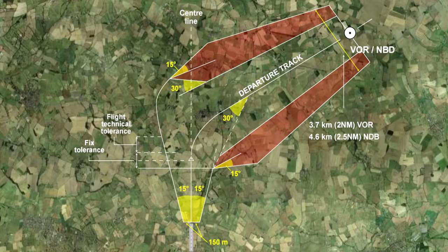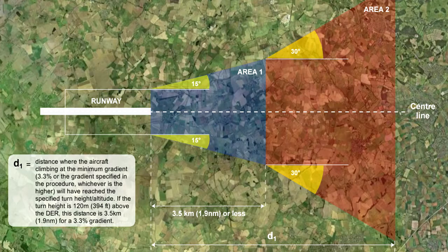In the event of in-flight emergencies, post V1, aircraft operators are required to provide contingencies that deal with safe operation of the aircraft during this phase of flight. An omnidirectional departure procedure is designed when no track guidance for departure is available. Departure criteria are developed using undefined omnidirectional initial departure tracks.